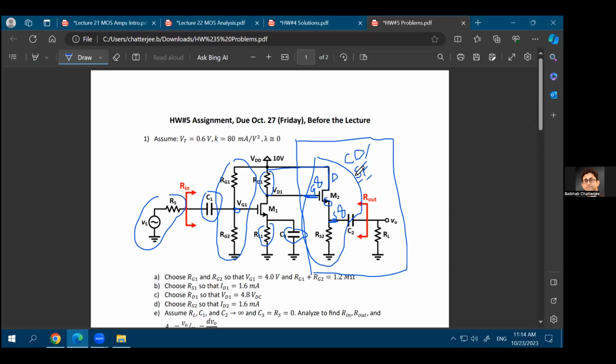Question? What would be the purpose of having it? Great question. So if the gain is equal to 1, what's the purpose of having it anyway? Because it's not being used as an amplifier. Why this is usually used is to drive a certain amount of load. So for example, let's say this resistance is very small. So let's just think about a spectrum analyzer or an oscilloscope which is in 50 ohm.